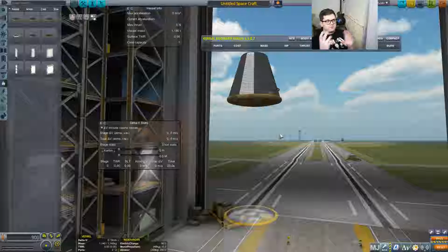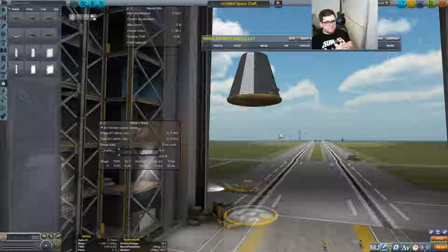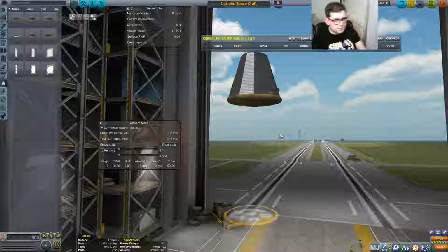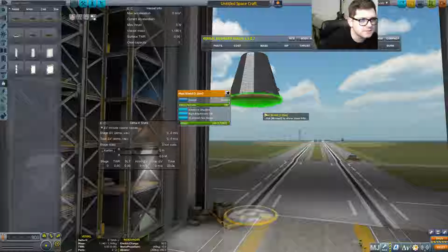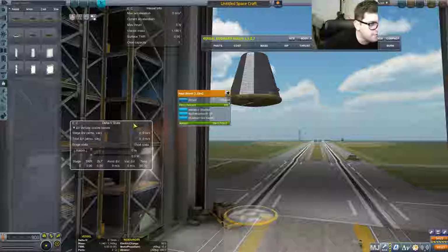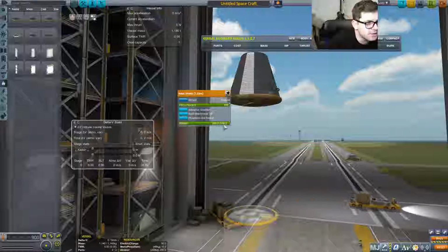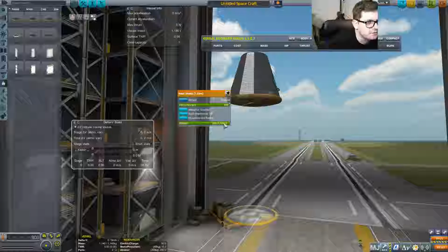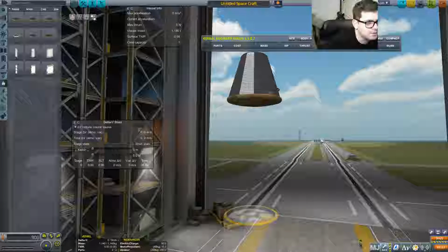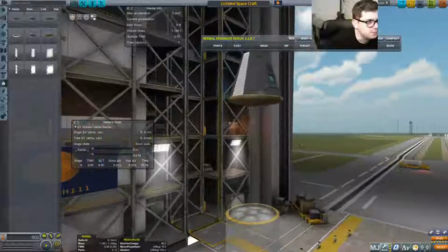That just demonstrated how good it was at containing and managing heat for atmospheric re-entry. So we've now got this ablative material. The faster and hotter that you come in, the faster this wears down. So you need to be careful that you don't come in too hot, because you will wear this ablator down, and once it's worn down, it will not protect you anymore.